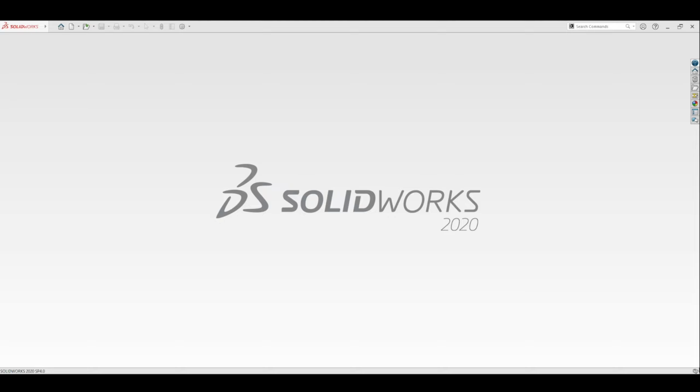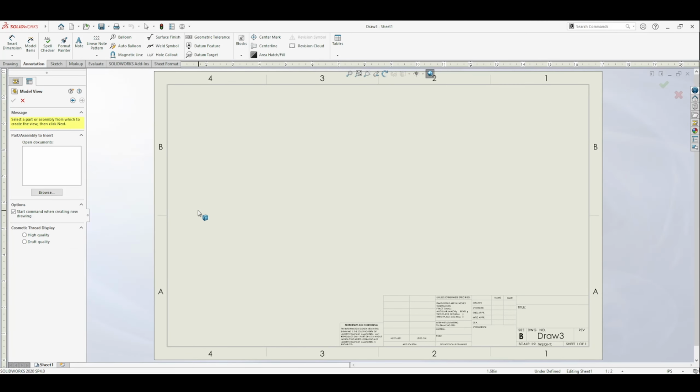On this assignment, we'll be creating a customized title block for our drawings moving forward. So you'll want to create a drawing. You'll go up to New, and just hit New, just Drawing Template, and hit OK. Typically, you would have a menu that would come up to select what size of drawing template you'd like. But this is how my program's set up right here.